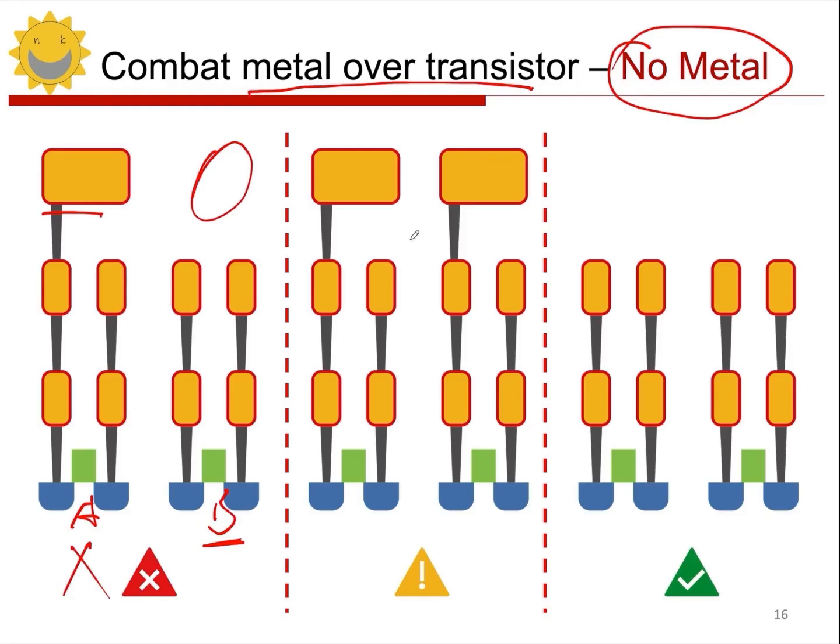Then let's look at the middle situation. In this middle situation, the two transistors A and B are both covered with metal. Did you see that? I've covered both with metal, so in this case both A and B will be affected by this barrier, which will influence the injection of hydrogen and the hydrogen annealing phenomenon. So both devices A and B will be impacted. The conditions are the same, right? The impact is the same. So, theoretically, A and B will be more consistent with each other, which means the matching degree will be better.